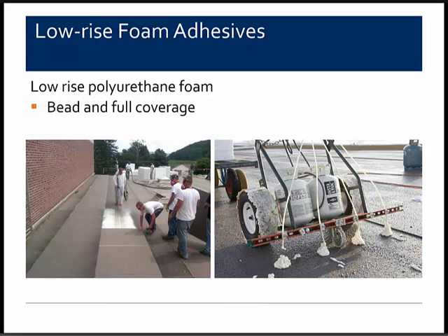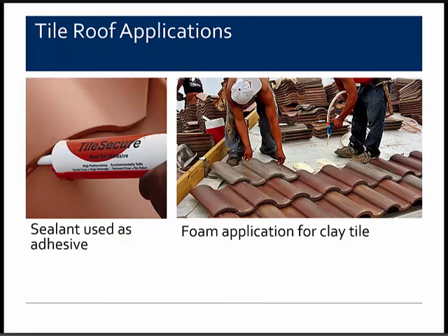And we also see some adhesives used in the steep slope market, foam application, particularly in southern Florida, where we have some very high wind loads to resist. Or in this case, it is being used to spot adhere the clay tile to the underlayment. And we're also seeing some sealants used as adhesives to basically seal or adhere the leading edge of the clay tile. However, intuitively, that seems to defeat the purpose of allowing water to flow from one tile to the next. It seems like it may trap water, making that underlayment integrity paramount to the success of the roof.